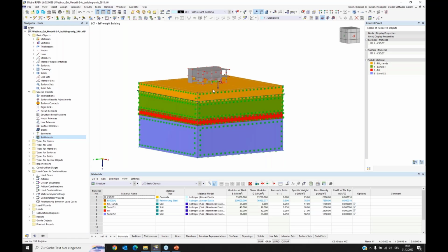They were generated from the information that comes from the borehole. Yeah, and if we would have more boreholes, it would use spline functions and NURBS surfaces to generate the different layers, surfaces between the different layers of the massif. I showed this more in detail in the last webinar. Today I only want to use one borehole.